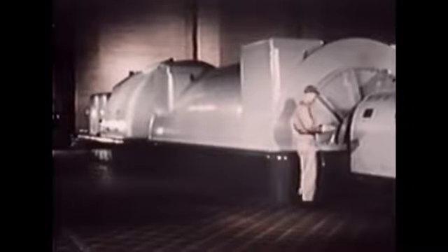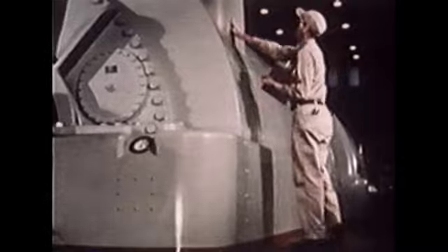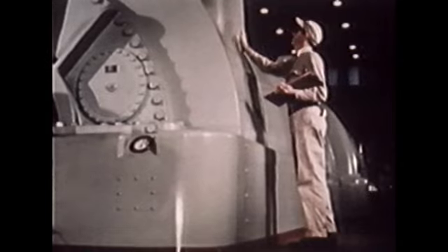Let's now compare the AC generator with the DC generator. The AC generator is used for the generation of most of our power because it can be built with larger power and voltage ratings. A steam turbine generator might be rated at 500 million watts and 13,800 volts. This high power and voltage is possible because the generator's output connections are attached to the stator, or stationary part of the generator. The rotor, which provides the magnetic field, is supplied with direct current of possibly 500 volts.